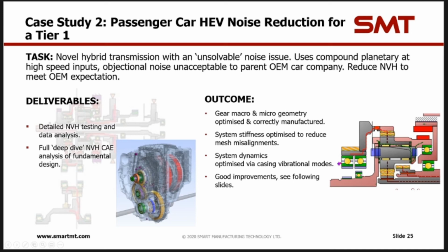The problems were associated with, again, system stiffness. So we optimized the support of the transfer gear set pinion support, as well as the planetary gear support. We optimized the macro and micro geometry of the planetary gear sets and transfer gear sets.